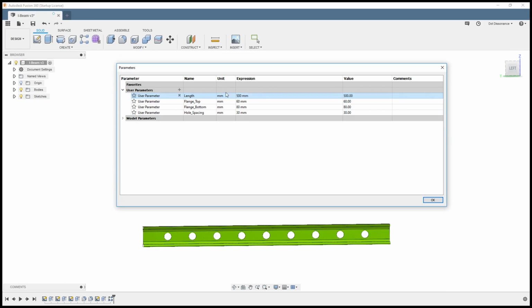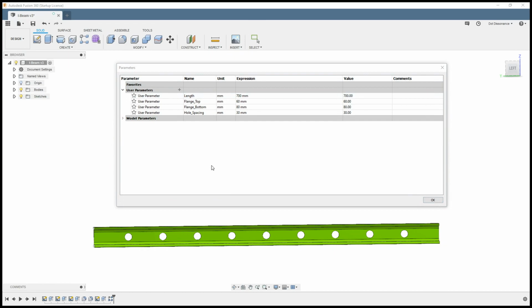You see the holes shrink with it, right? Go to, whoops, just a single click. 700. Everything kind of stretches out. Cool deal. But now, let's say that as we stretch this out further and further, the holes, I mean, they're not really lightening holes any longer. They're just kind of like a couple little holes here and there. So we want to keep them a bit closer together.